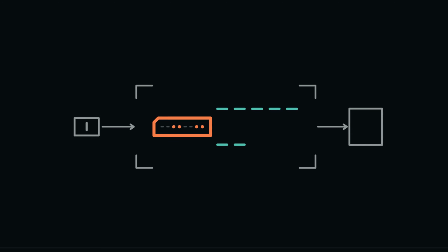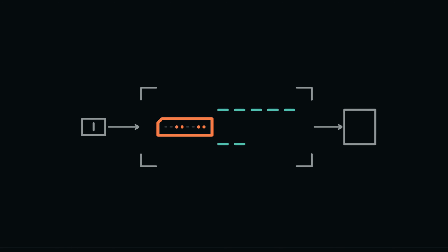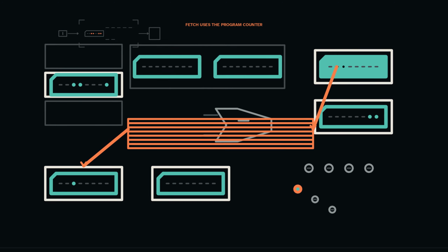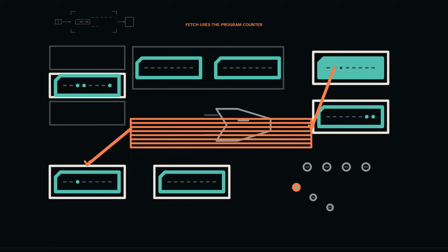Nothing needs to leave the frame while we build it. PC, MAR, MDR, instruction register 0, instruction register 1, controller state, R0, flags, memory event, and the 1 active bus transfer keep fixed positions in the ledger. The clock supplies the recurring edge, but it does not decide what each edge means. Controller state supplies that decision.